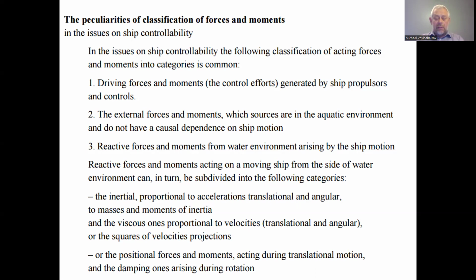I have to underline that usually, to determine the elements of the ship motion in the water by solution of the differential equations, the hypothesis of linearity is adopted, that is, the damping forces are assumed proportional to the first degree of the velocities, not to the square degree.